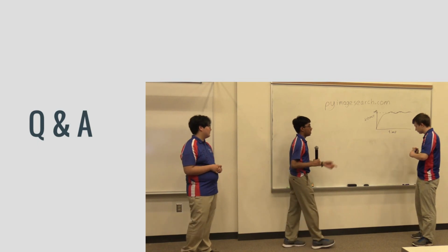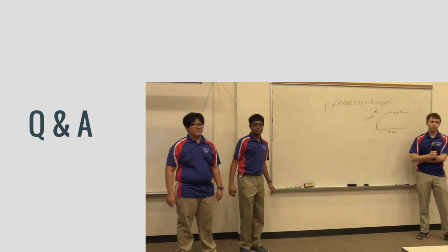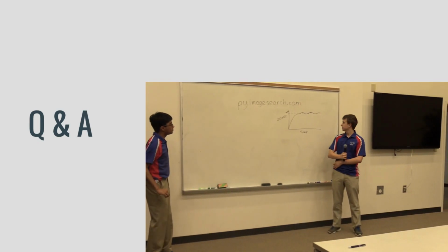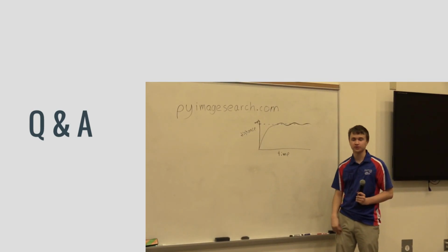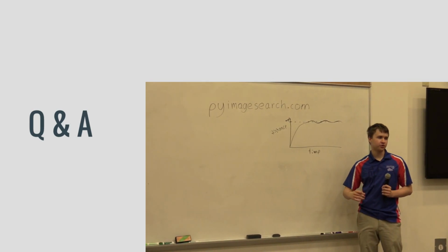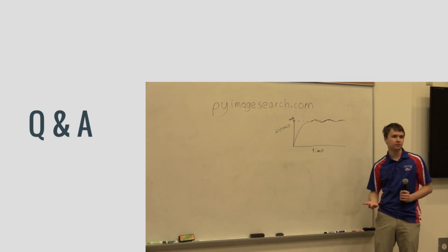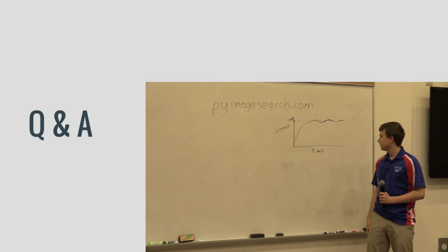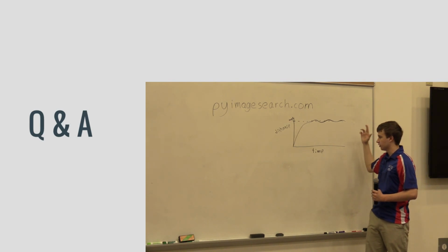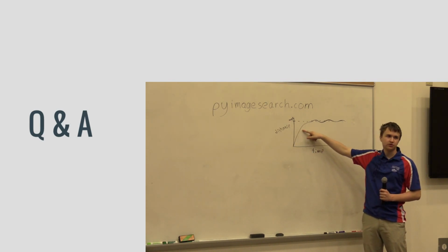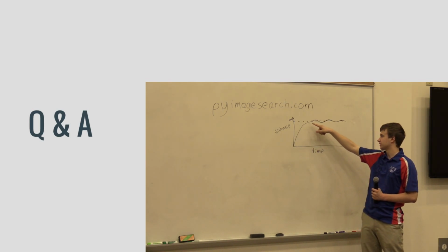So Chris here has a drawing. Basically, the way PID works is you have a motor and some way of measuring a statistic on that motor, like distance. In the code, a lot of this is pre-set up in WPILib. This is difficult, but it comes kind of pre-built. You tell it, I want to go to this target value on this sensor, and it will start running that motor, and as it runs, it continuously corrects itself to best hit that target. It'll start very fast, and it'll ramp down as it gets to it.